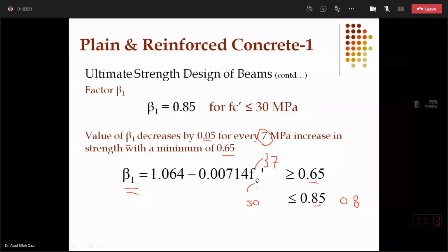There is a perfect agreement between your model and the experimental curve. Then do the integration to get the area under the curve. Then divide that area by 0.003, or the ultimate strain you have captured by actually performing the test, corresponding to 85% of the peak, what was the strain. And then finally you get f average of that concrete which is above 30 megapascal. So this can be done in the laboratory by performing tests on cylinders.